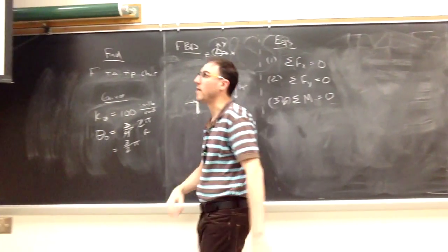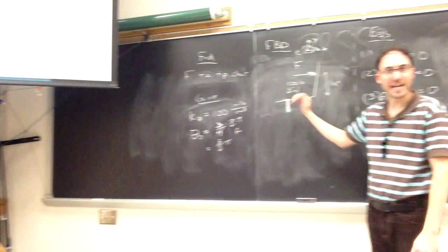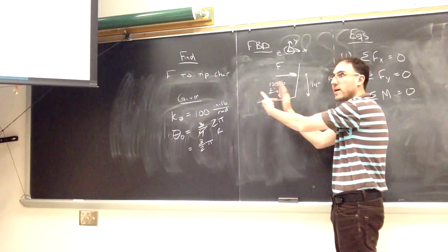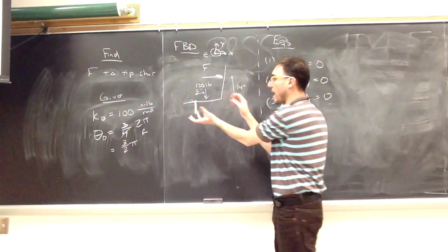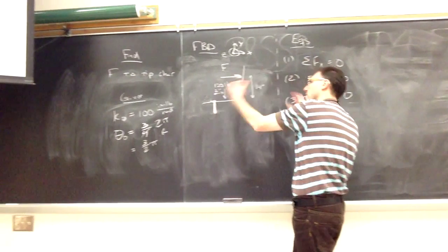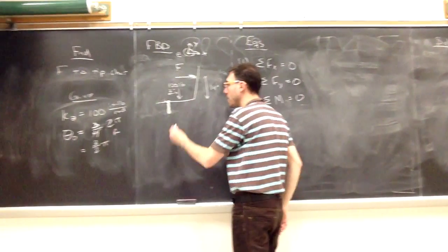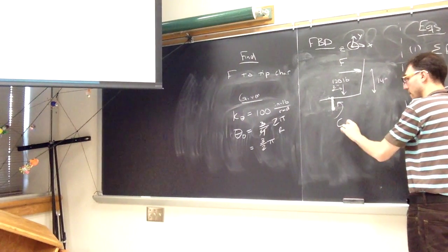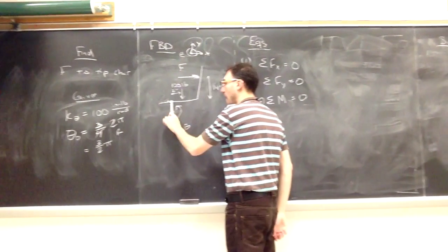If we look at that little stopper at A, a counterclockwise moment would be rotating the chair forward into that stopper at A. If it was imparting a moment in the other direction, it would want the chair to rotate backwards, and that's, at least for this design, not what we want. So we know that spring is turned in such a way, I'll call that C sub B, that it's imparting a moment counterclockwise at the post at point B.